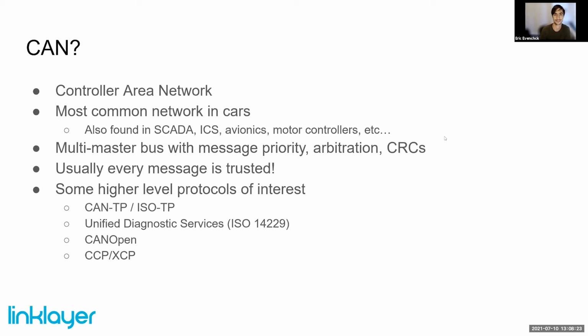Every diagnostic feature that your dealership can do is done over this. So everything from reflashing controllers to calibrating sensors. You can do things like dump the airbag recorded data using this protocol on some vehicles. You can even deploy the airbags using this protocol on some vehicles. So yeah, there's a lot of functionality that's baked into there.